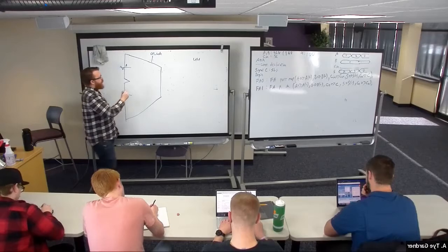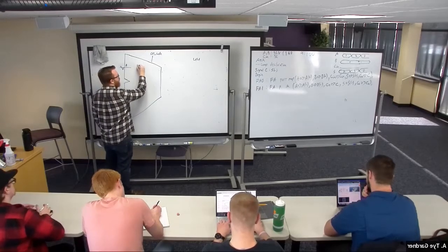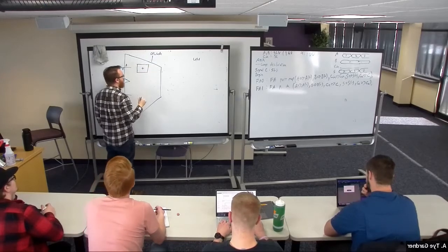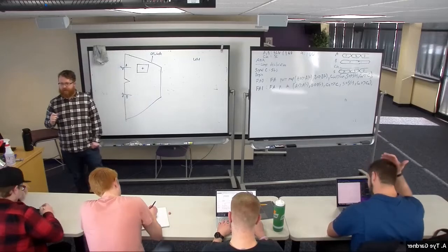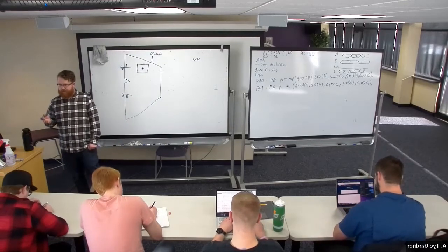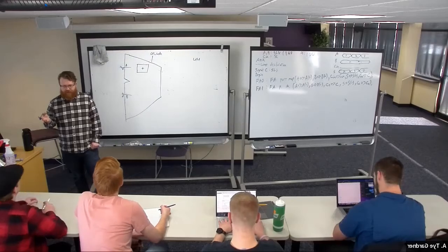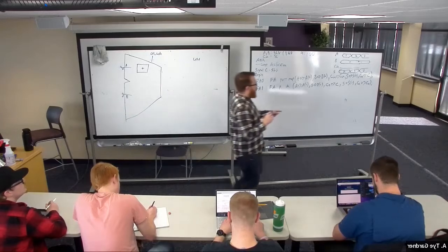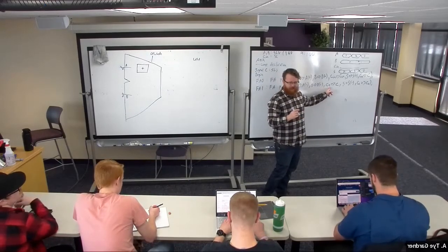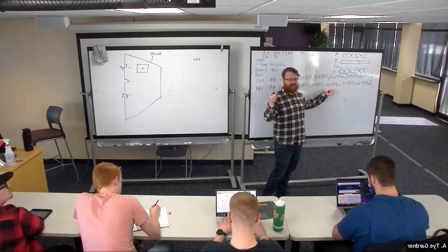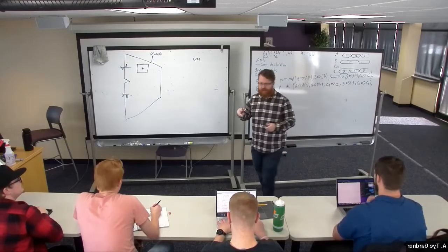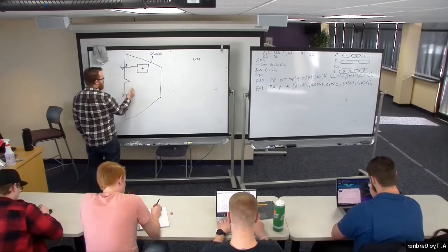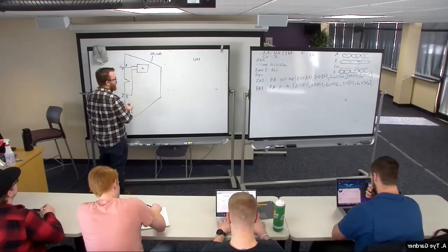Well, what it's going to do is first off, it's going to have an adder in it, but it's going to be an 8-bit adder, okay? Which is easy once you finish your 4-bit adder, right? You just stick 2 4-bit adders together and you're done, as long as you don't tie your first one to ground. If you tie your first 4-bit adder to ground inside of the 4-bit adder, it won't work to stitch them together. Otherwise, it's pretty easy. What it's going to do is add A plus B.